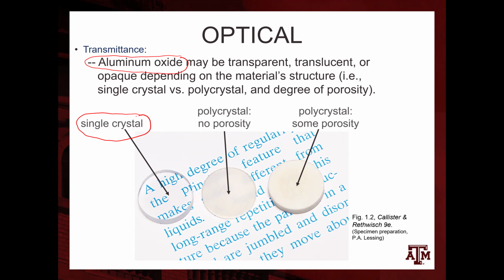So if we have just grains, we can see the material is almost semi-transparent. But if we also have porosity, that means there are many microstructure features, grain boundaries and grains and pores and their interfaces, and that gives a much higher probability of scattering of those photons, and the material becomes opaque. So again, it's the same material, same composition. We didn't change anything